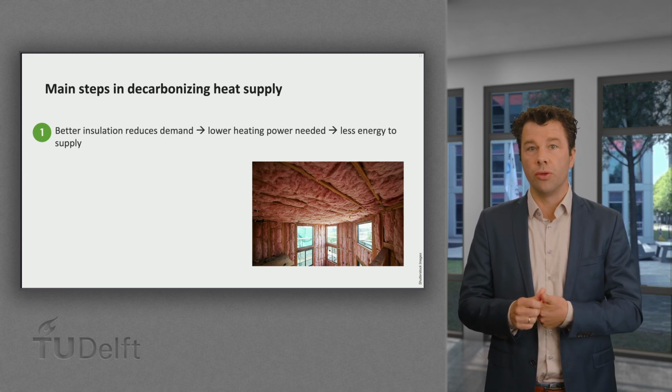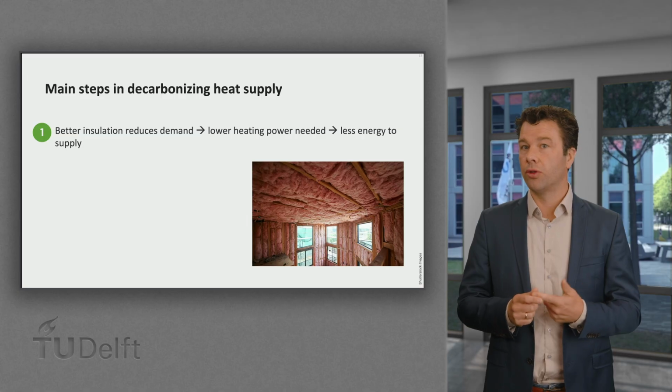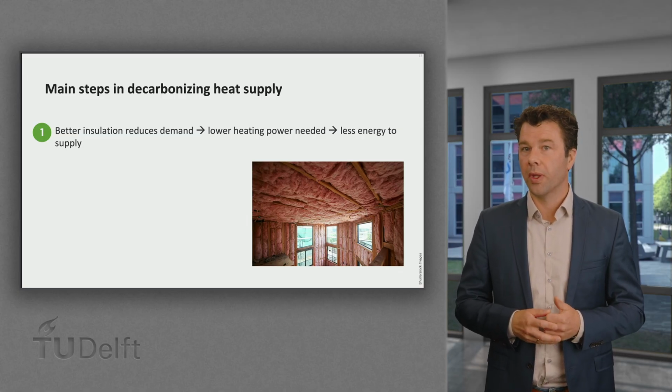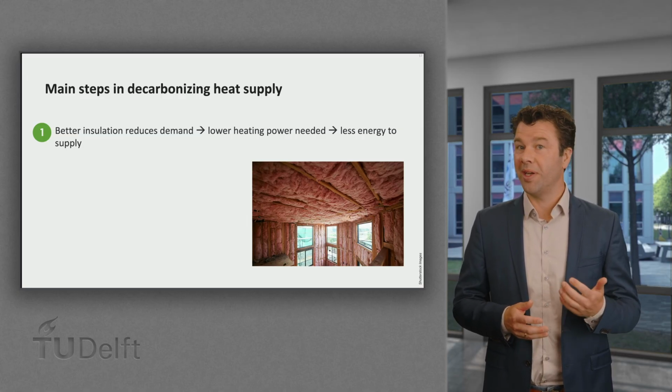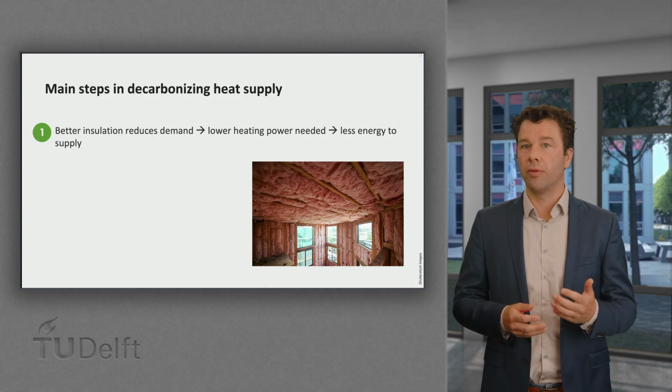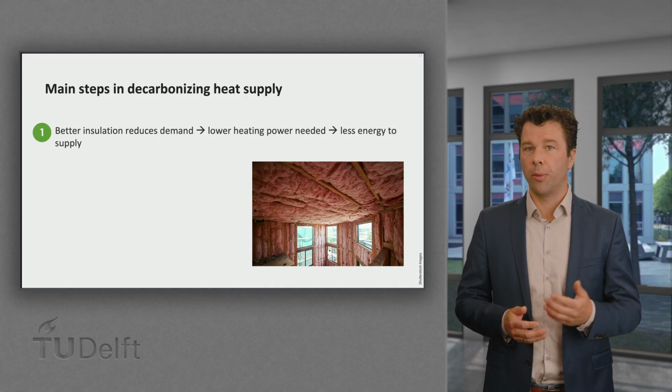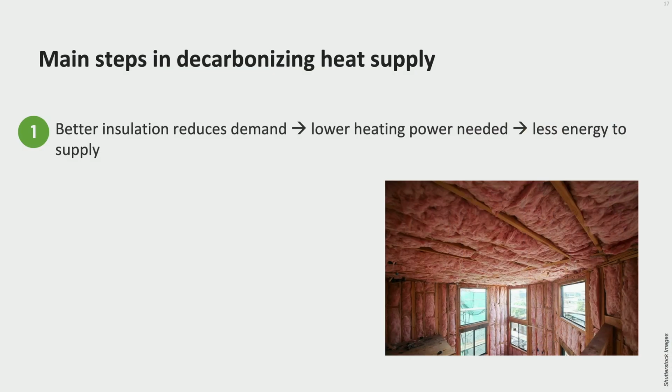The first is to reduce peak heating demand, as also discussed in previous lessons. This seems like an open door, but many people, including professionals in the field, often forget. This is commonly done by insulating, which has a major added benefit that it will also reduce the total required heating demand.